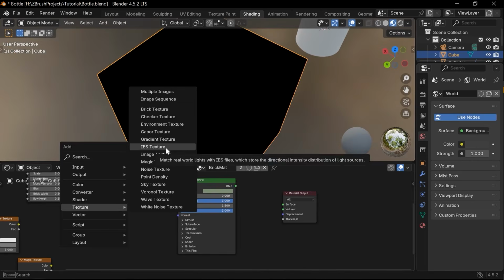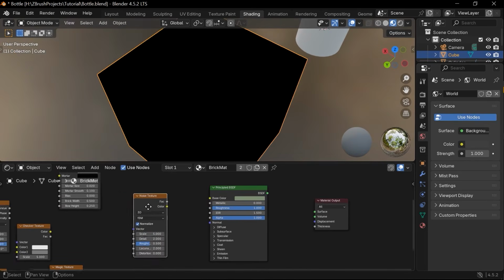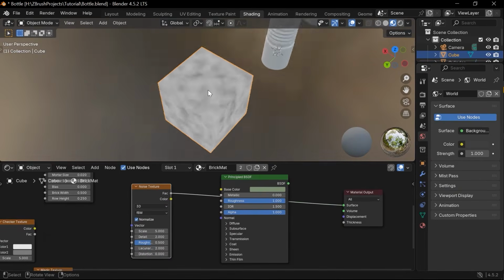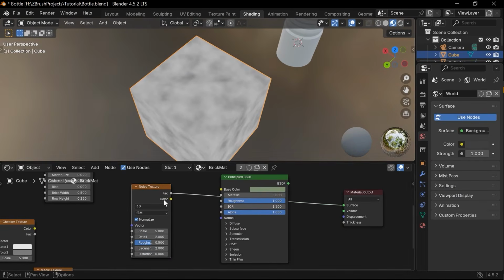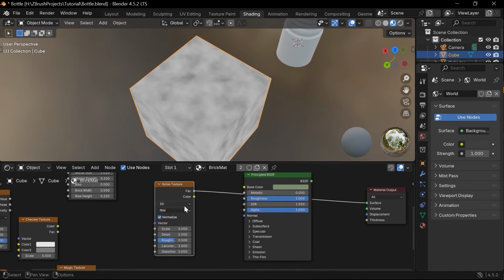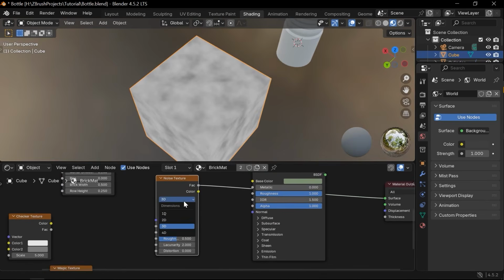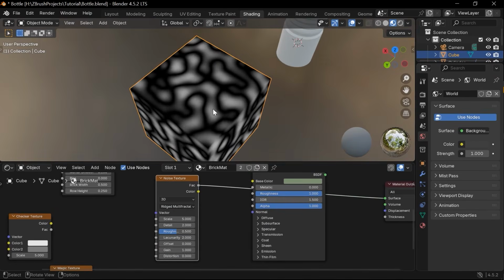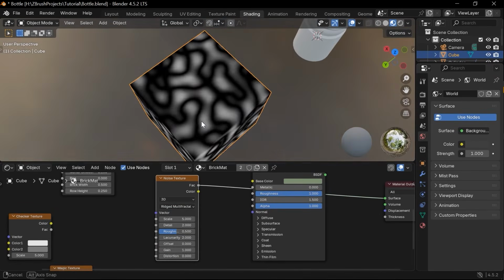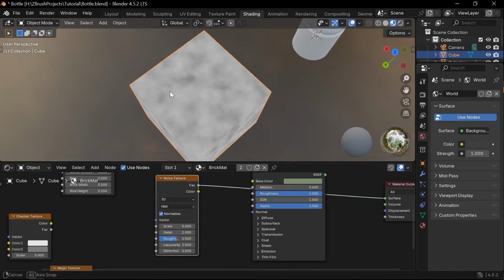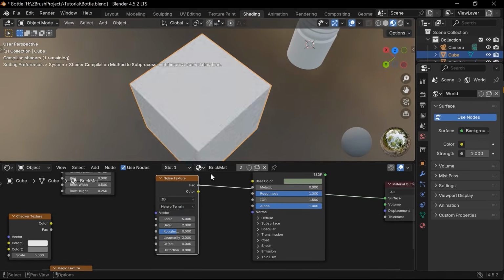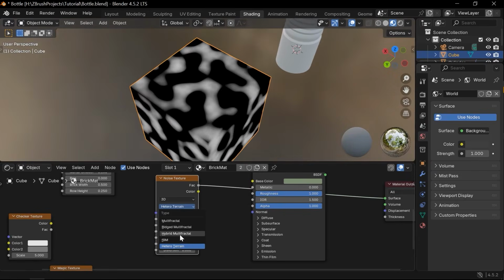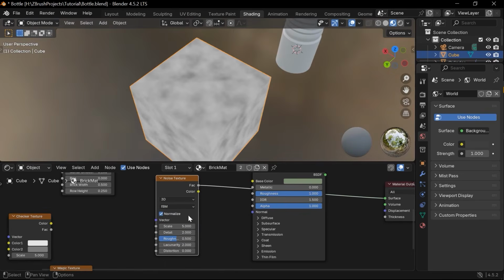Alright, the next texture is the Noise Texture. It is the most important and useful texture in Blender. Here you have an unstructured noise texture. We can change its type: 3D, 2D, 4D, 1D. I will just focus on 3D for now. We can change its shape: multifractal, ridged multifractal, which gives you some black waves, hybrid multifractal, FBM, which is the default type, and hetero terrain, which looks like the hybrid multifractal. You need to choose based on your needs.